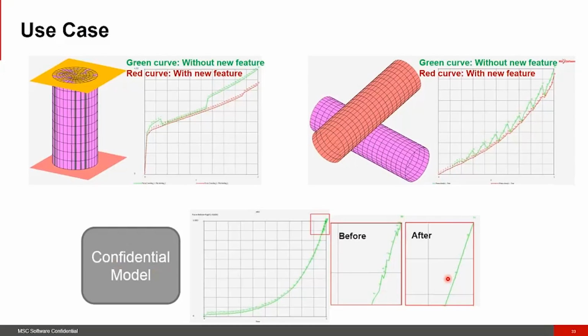So the local convergence option, I really encourage you to try if you're running a model. You do pay a small penalty in the fact that you're doing an additional check. Again, it'll depend on problem size, how big that is.